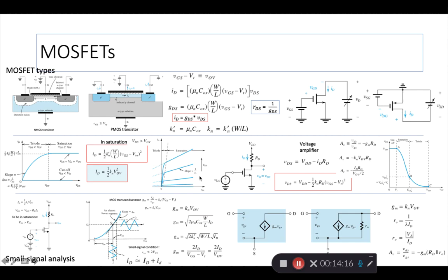Okay. We have this other set of graphs which connect the VDS to ID, but for different values of the gate to source voltage. So for different VGS, right? This is one VGS, this is another VGS. You can draw different shapes of these, and that also has its own use. It helps to create this VTC graph, which we'll come to in a minute. So I hope these graphs are clear.